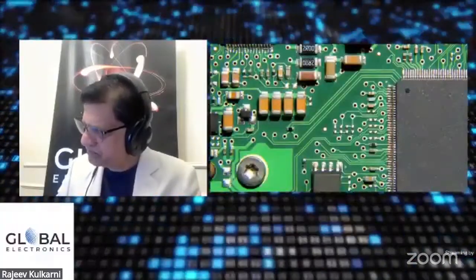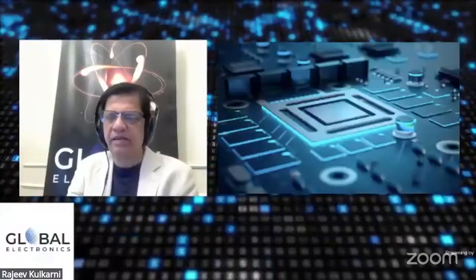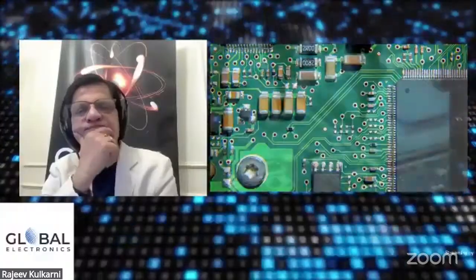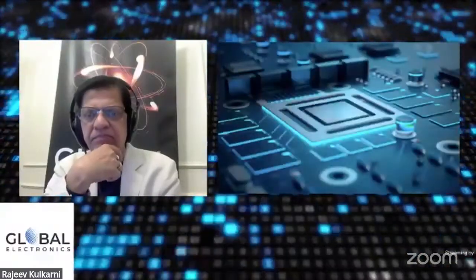Anyway, they can call me also directly, not an issue, over my phone, or they can put a question to the channel. We will definitely answer this. This is a very good question. Go for a wider trace. Go for a very smooth copper. Even if the PCB vendor or CAM vendor gives you pure 100 ohm, you tune it to 96 ohms. We are getting a bonus of a few extra microns of width. That will definitely help you on the day.